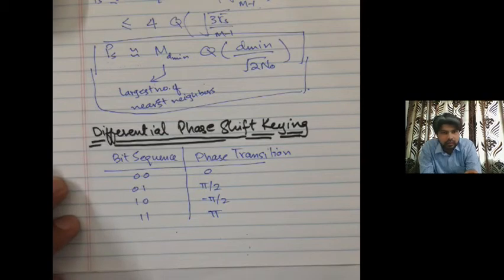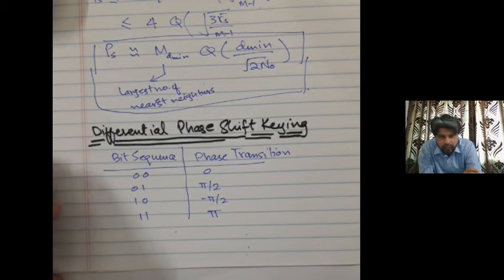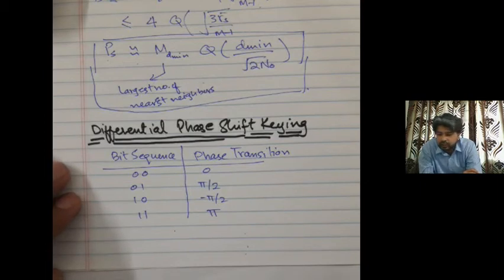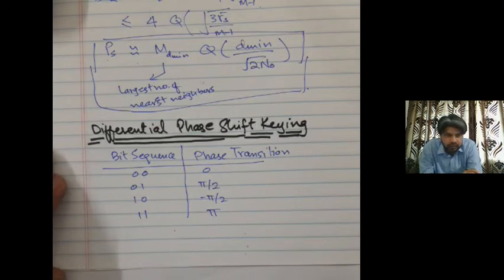That means you look at what phase was transmitted in the previous symbol, and whether or not you have any phase transition in the current symbol. And if you don't have a phase transition, you decode the information as 0 0. If you have a transition of 0 1, you say that 0 1 was transmitted. So of course you need a phase comparator or devices of that sort in order to decode that information.